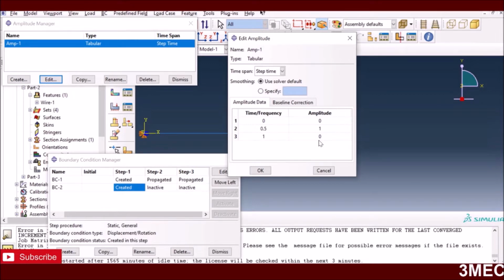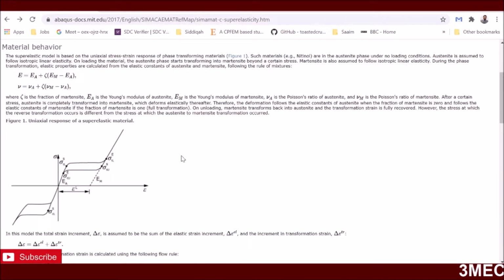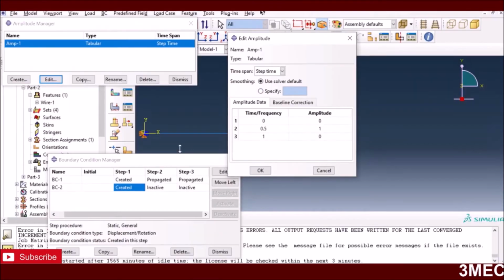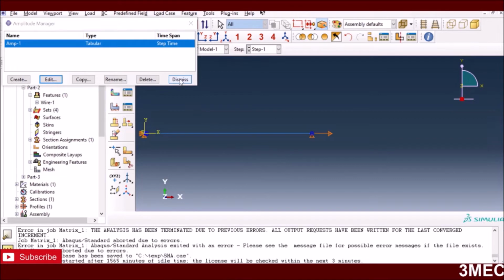So I'm just trying to show you that my curve which was shown here can be predicted based on shape memory alloy properties of superelastic response in this case, because we are just trying to learn. This is the first step you always do. Rather than starting this complicated analysis, you first learn how do you model the shape memory alloy, how do you model the matrix material, how do you model the interface fracture in the matrix using node release technique, and then you combine everything together rather than start with the complex stuff. So everything is done incrementally.